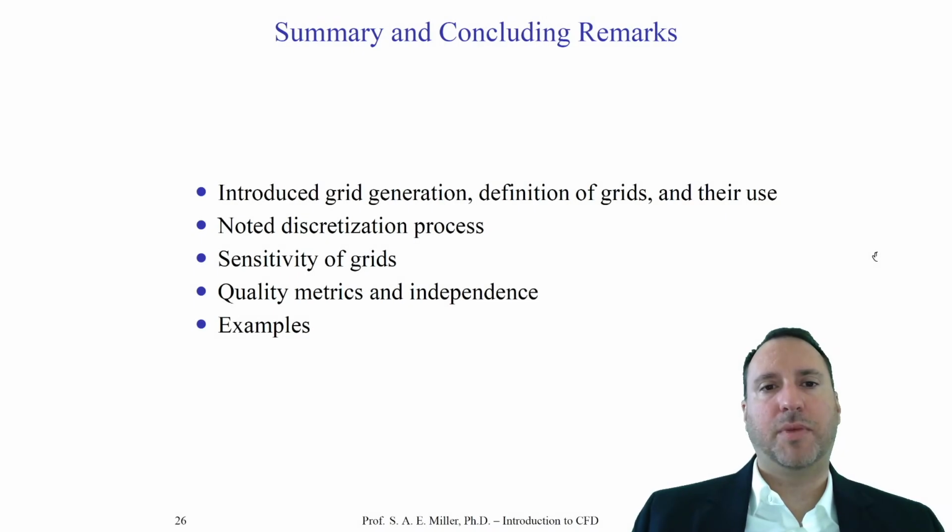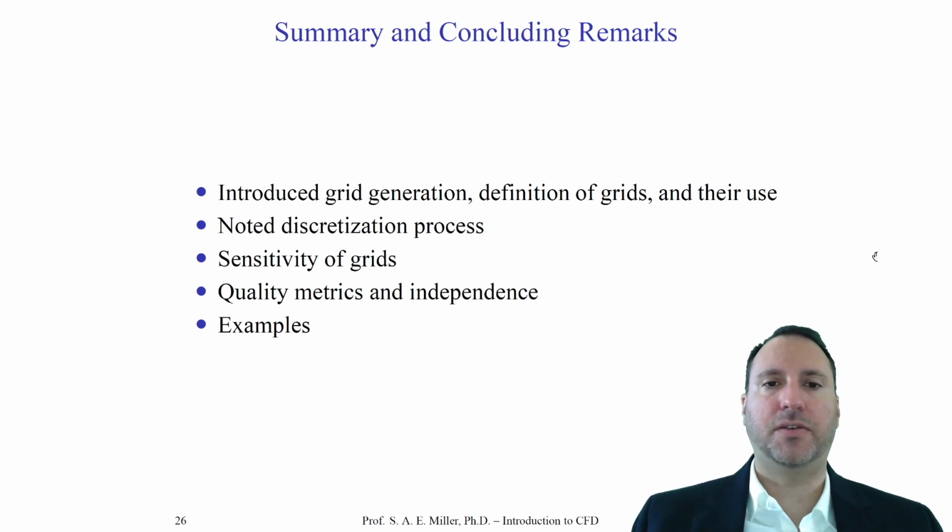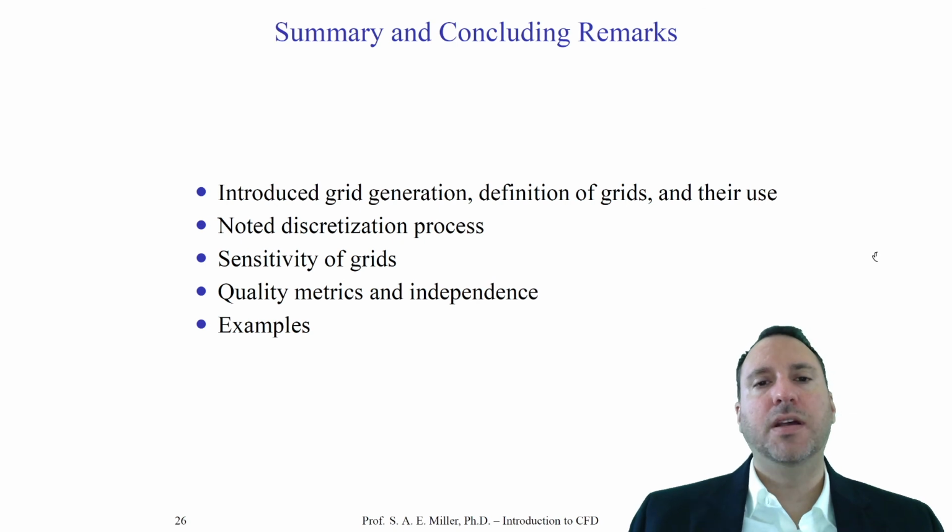Let's summarize and talk about what we discussed today. We introduced the most basic concepts of grid generation. Remember, in a computational grid generation process, you need to find some fluid volume with no holes, that it's watertight, define the surfaces, and create a surface mesh if you're in 3 dimensions. If you're in 2 dimensions, your surface mesh is the grid that's used by the solver. In 3 dimensions, once you have your surface meshes with grids and connectivity, then you create a volume mesh interior.